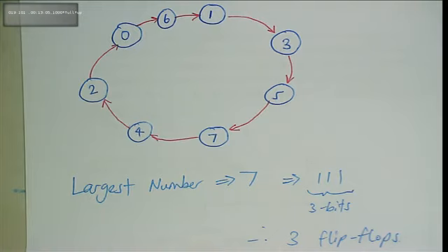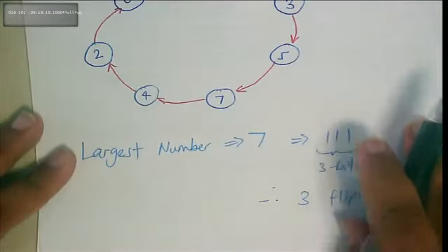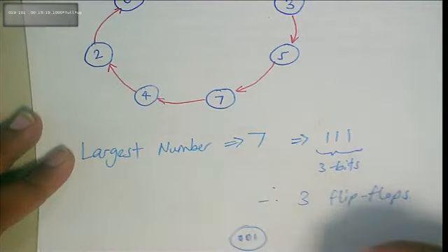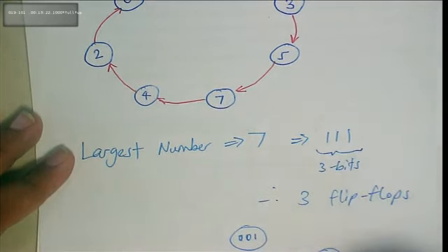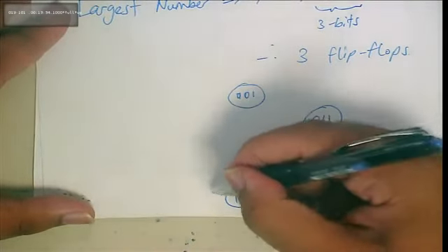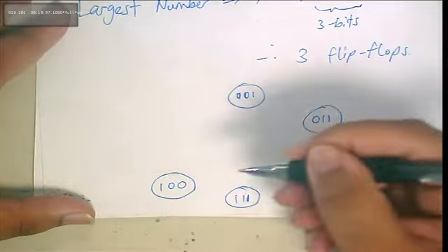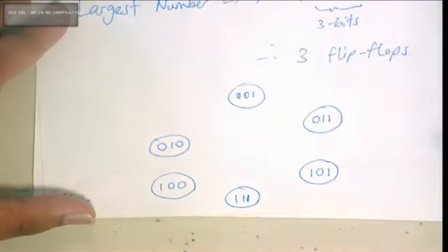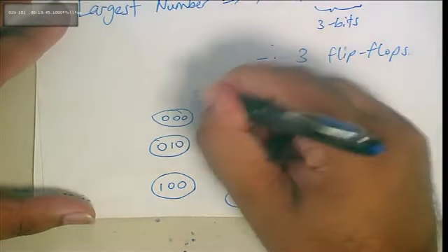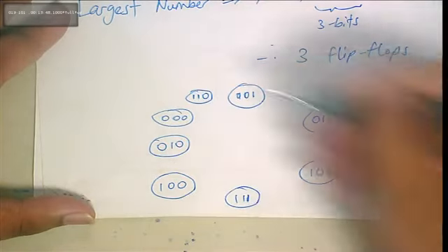Okay, now, let's now convert our state diagram. That was a state diagram of the ring counter for our particular problem. Now, so let's do it. So that's 0, 0, 1. There'll be 0, 1, 1. Next is number 5, yeah? What's that? 1, 0, 1. 1, 1, 1. Yeah, 1, 1, 1. Then the next one is 1, 0, 0. Next one, 0, 1, 0. Next one, 0, 0, 0. Next one, 1, 1, 0. Is that right?